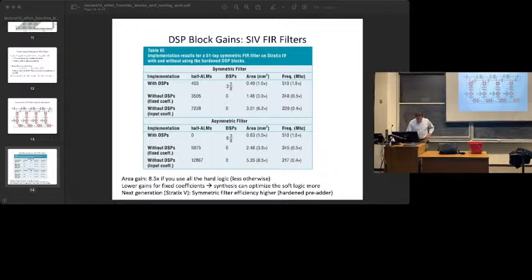Now the next generation after this of DSP blocks from Altera basically pulled in these adders. Okay, so the generation after that, they went, oh, these symmetric filters, we can make them even more efficient if we stick that in the DSP block, so they did that. It makes the DSP block a little bit bigger, but adders aren't that big, so they were able to do it, not add many routing ports, so it was still a net win. So these numbers, the reason I'm showing these, are also a useful check on some of the papers we looked at early on, what's the benefit of hardening.